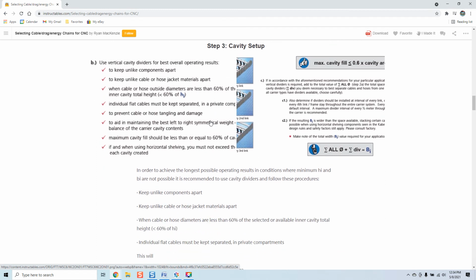The big thing here is that we make sure that the cable chain is properly set so that we allow all of our cables up to their minimum bend radius. Now, that's another term used where many guys don't even know what I'm talking about. Every cable in production, regardless of what it's used for, what genre, has a minimum bend radius. Smaller cables in diameter have a larger minimum bend radius. Larger cables in diameter have a smaller cable minimum bend radius, or excuse me, a larger minimum cable bend radius. And that's due to the fact that naturally its diameter is larger.